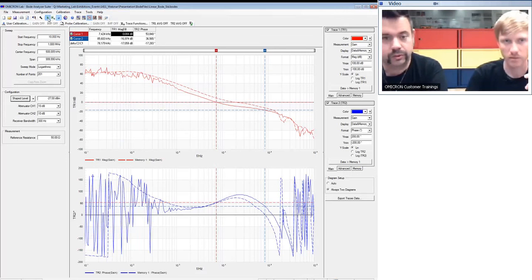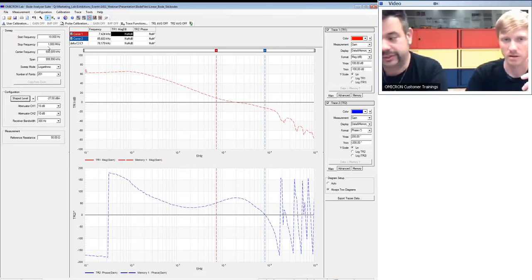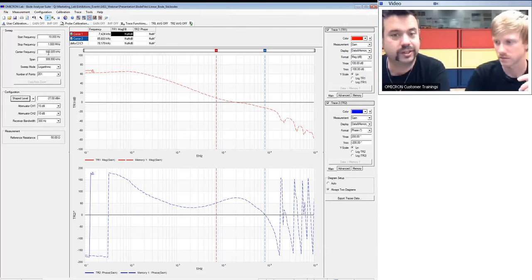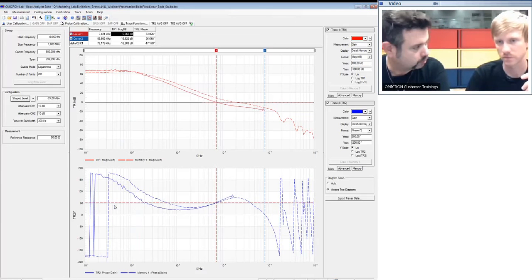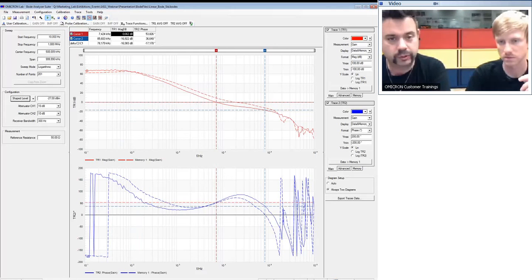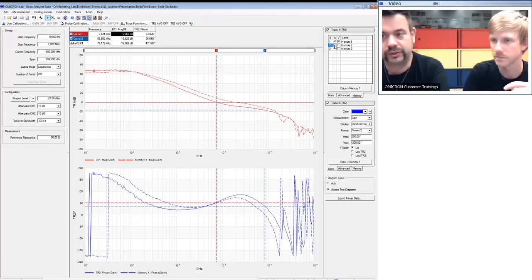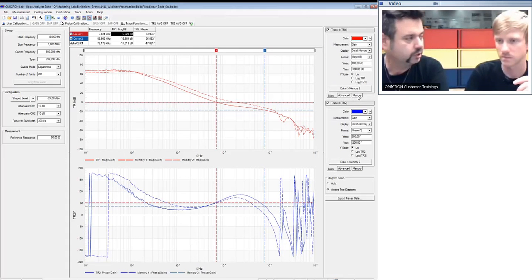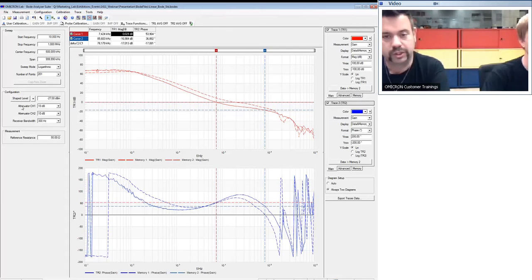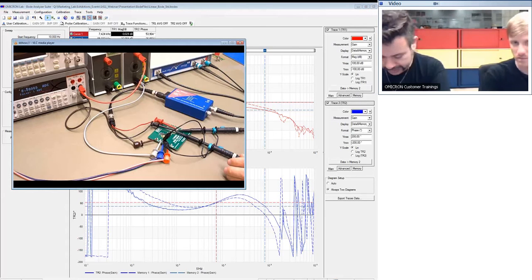So when you perform measurements, you have seen it's important that you look at the load current and that you look at the temperature. Another point to look at is the supply voltage. If you have a certain supply voltage range, you also have to do some more measurements, so you might end up with a lot of different measurements. You have to measure at the minimum load and then the maximum load with standard supply voltage, then you do the same with the minimum supply voltage, and you do the same with the maximum supply voltage. So there's a lot of things to take into consideration before you can really say that the system is stable.